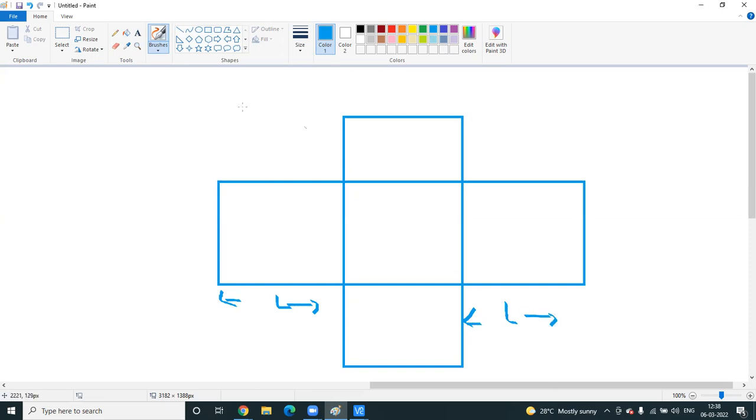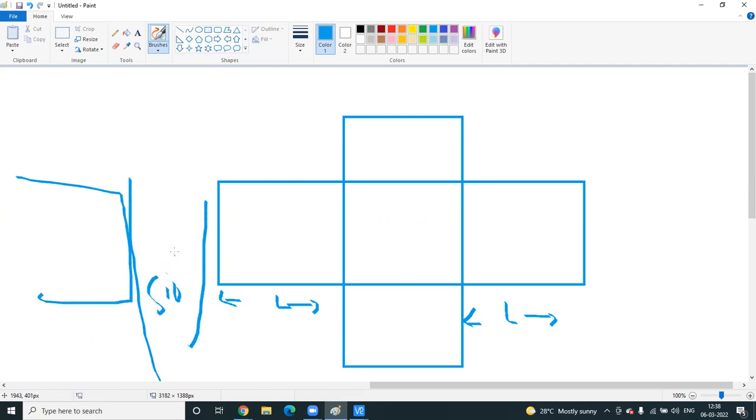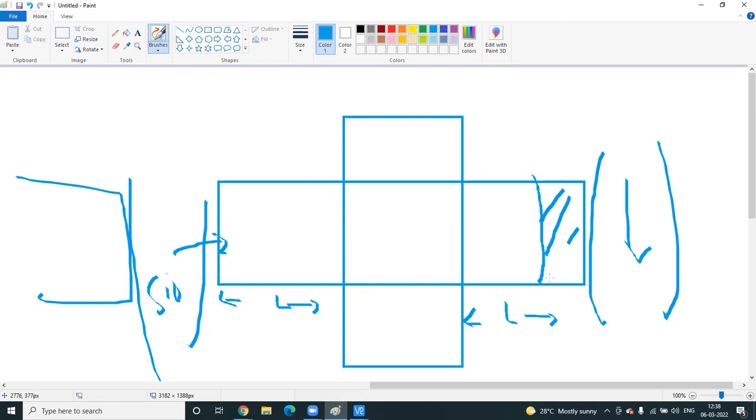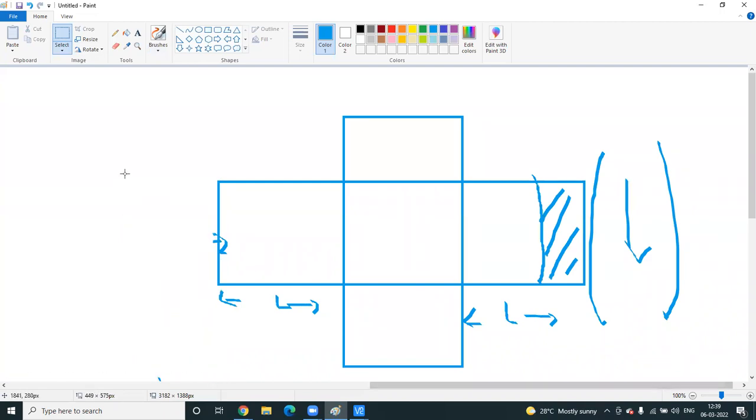If it is and another device are there, in between SiO2 layer will be there. Due to this SiO2 layer, this channel length will be reduced. Sorry, source and drain length reduced. So what will happen? That time LOD effect will occur. To avoid this LOD effect, you use dummy on the side. Are you getting the point? This is the oxide layer, so you are adding oxide layer.